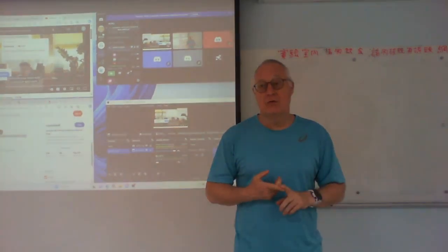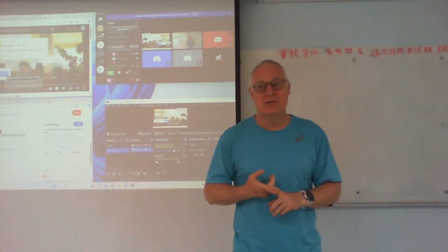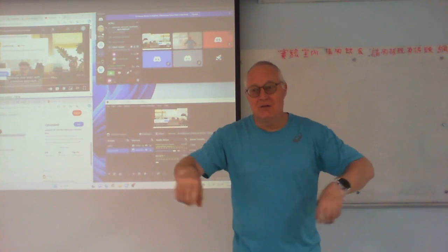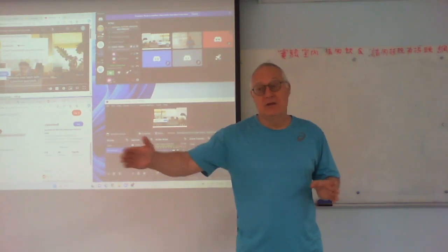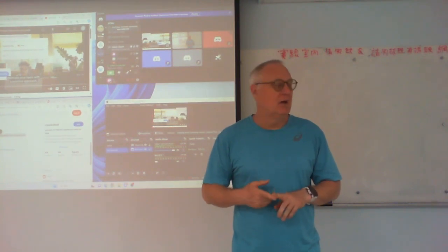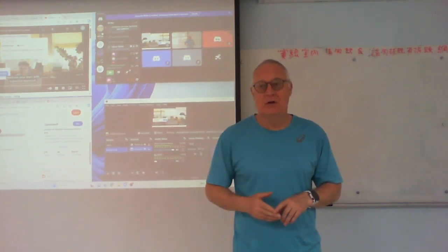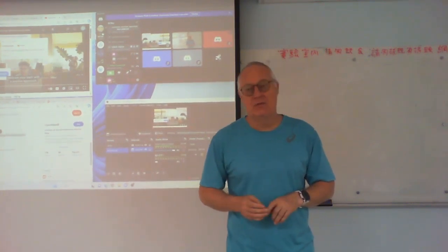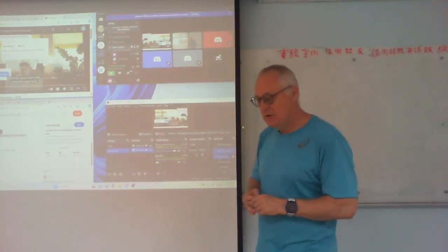GPS, of course, would work if we're outdoors and we have good GPS reception, but it's not really accurate enough. We need to have the velocity every time when we balance the scooter. We need it for more than the 5 to 10 meter accuracy that you get with GPS. IMUs were too noisy because of the road. It's not a flat surface that we drive on. So we actually use optical flow in order to measure our velocity.